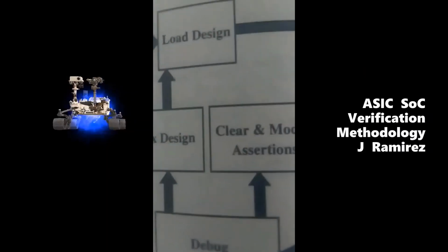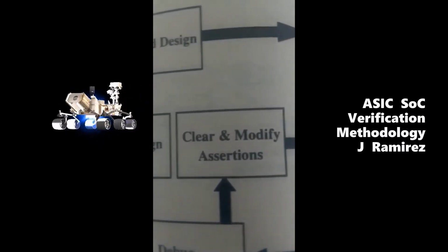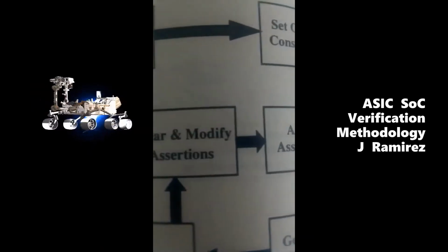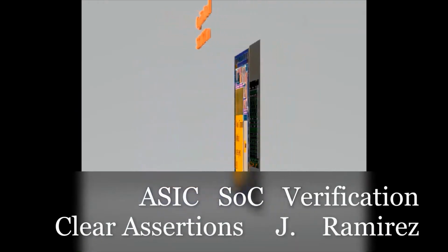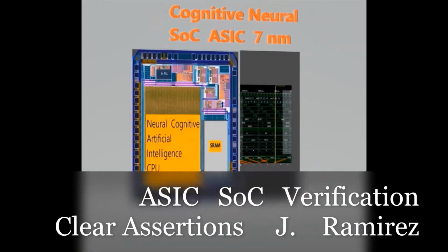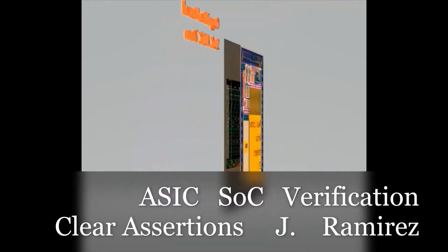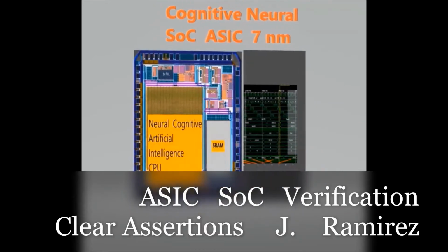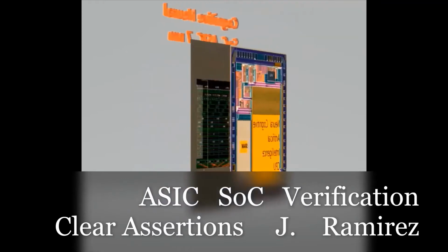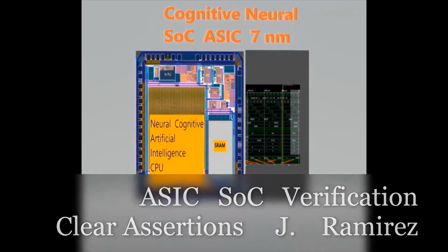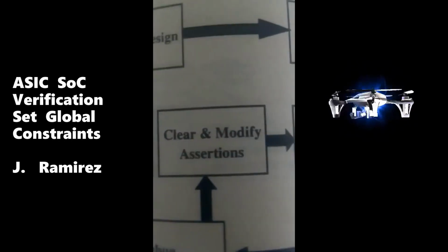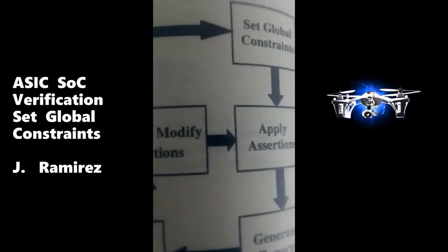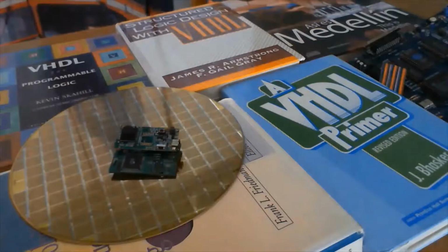As an example, a regular structure such as an adder may be very easy to envision and to lay out, since there is a high degree of parallelism among all of the bits of the adder. But the same adder, when synthesized, may not have this level of parallelism. Each bit can be constructed differently. This places some limits on the ability to do custom layout of synthesized logic.